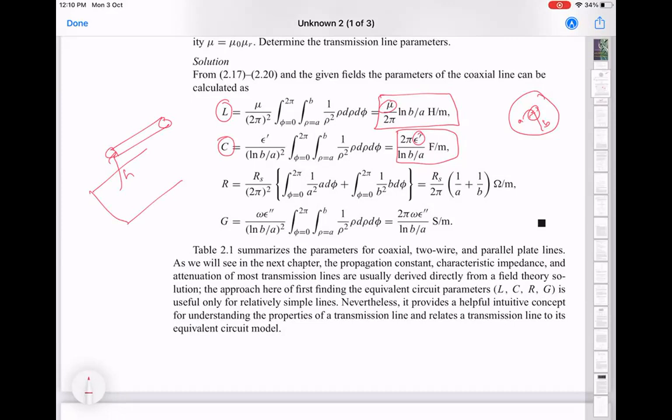If this was completely removed and it was just a wire, it will have the highest inductance per unit length. As you bring this other metal closer, it induces currents flowing in the opposite direction in the bottom. And effectively, you can think of this as giving a mutual inductance effect, which cancels the L in this main line. So that's the reason why making B bigger makes the inductance also go up. So it's a shielding effect of the presence of the second conductor.